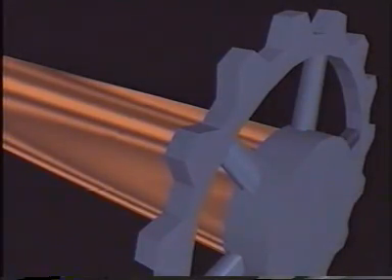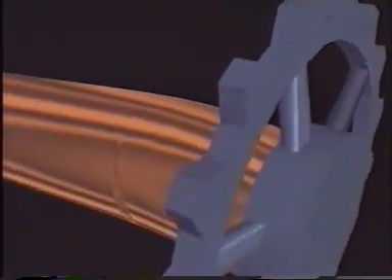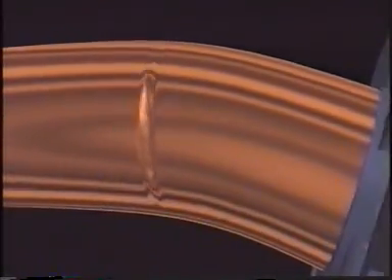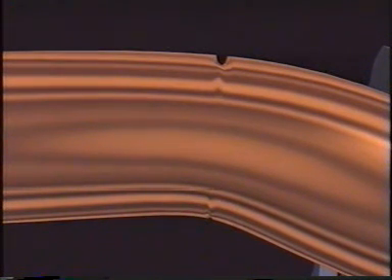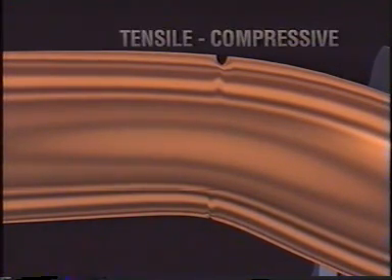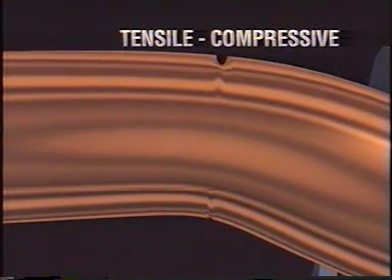And then consider rotational bending. A rotating round shaft is commonly subjected to a bending load, often in addition to the torsion of rotation. A unique feature of this rotational bending is that during one revolution of the shaft, both tensile and compressive loading are exerted alternately at each point on the surface around the entire circumference of the shaft. This occurs in the region of maximum bending moment.